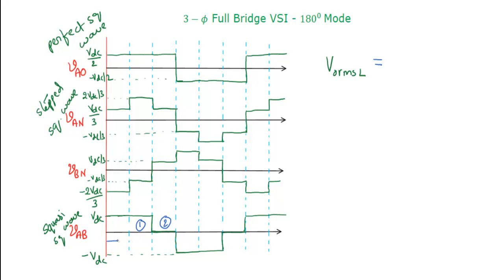So you can see that this wave is there for 120 degrees, okay, out of 180 degrees. You can consider that one. If you consider that one, as I told you, we need to take this root of, okay, the RMS value of segment 1. Segment 1 is nothing but a square wave. The square wave RMS value is VDC. V is like the maximum value. Maximum value you can take, that is nothing but VDC. VDC square multiplied with the available duration of this waveform. The available duration of this waveform is 120. 120 is nothing but 2 pi by 3.